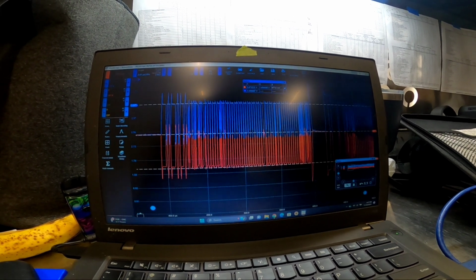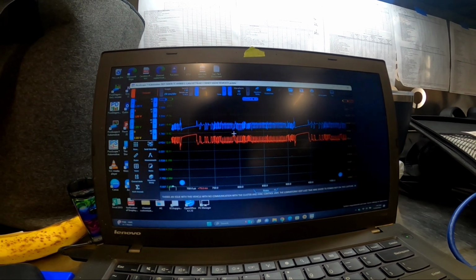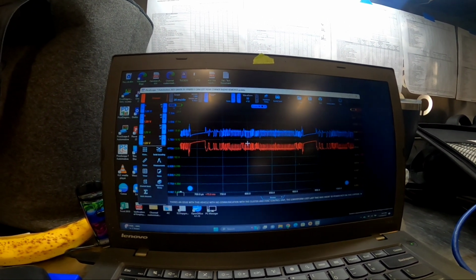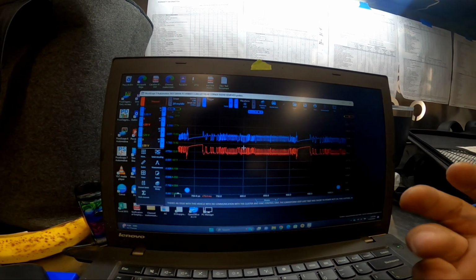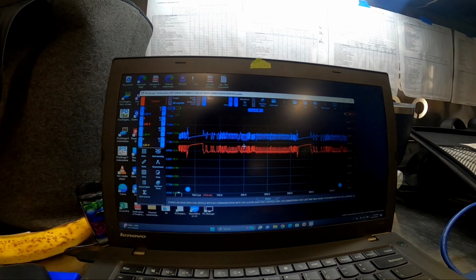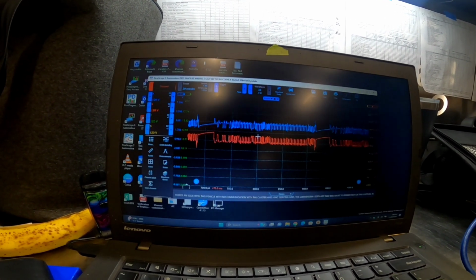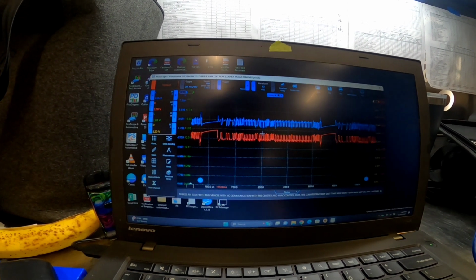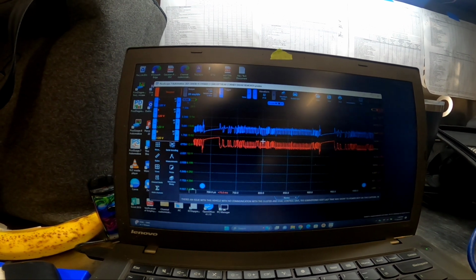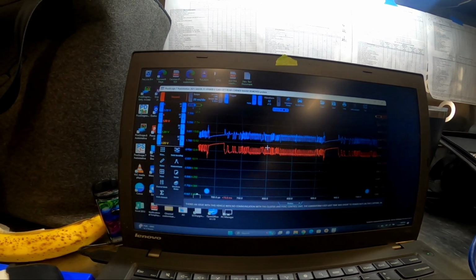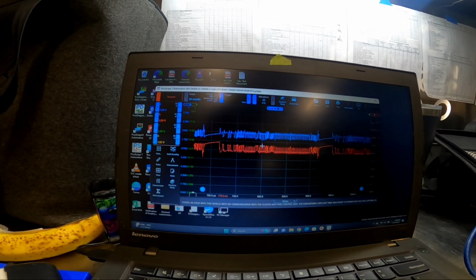And if I minimize this quickly, this is from when we were doing testing, right? I didn't capture the one when it was all plugged in and connected, but this is the one from when I unplugged the connector for the left rear corner radar. So right now it's fixed. I just did the variant coding on the left corner radar and calibration. Let's go to the cluster quickly just to make sure you can see that the left corner radar and the harness fixed the issue.